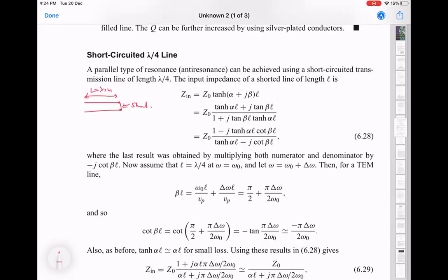So you can think of the short circuit. Now we have to picture this in the wave propagation picture, where we say, okay, voltage as a function of position or current as a function of position. Now, because this point is a short circuit, you know that the voltage here, and if we call this point x equal to 0, is always going to be 0.